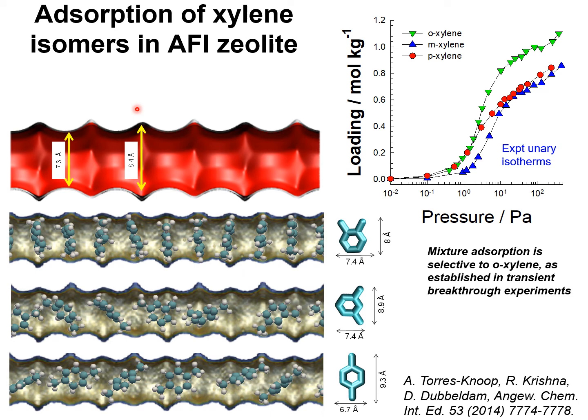Since the adsorption selectivity in favor of para-xylene that is obtainable with Barium-X zeolite is of the order of 2, it is of industrial importance to examine whether alternative materials such as zeolites and MOFs offer improvements in para-xylene selectivity and uptake capacity.